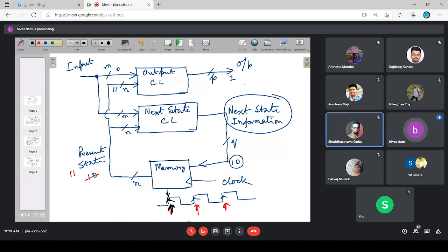Yes, sir. So the same is true in the case of a sequential digital circuit also. At the current time instant, what you are doing is, we know that the past history is saying that the first 2 bits of the sequence are available. Where from are you identifying that? From the present state. And you know that the present input is 0. Where from do you know that? From the present x value. So from these two considerations, you know that my current output should be 1.